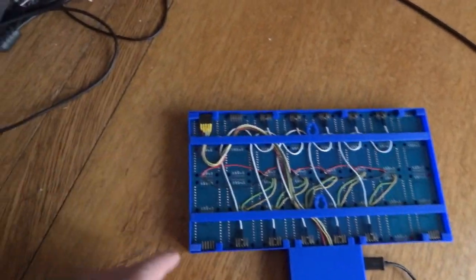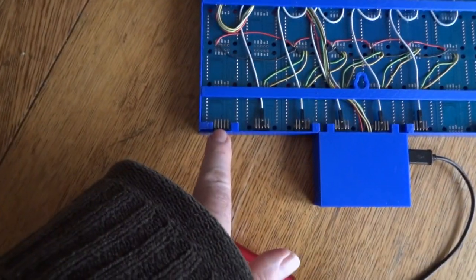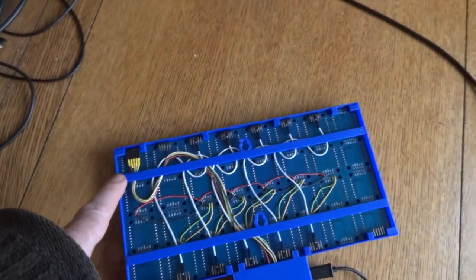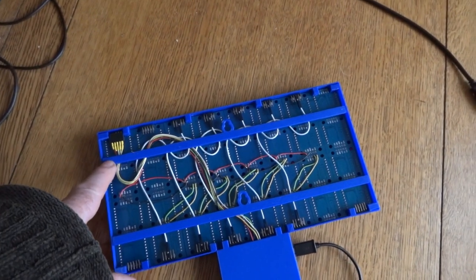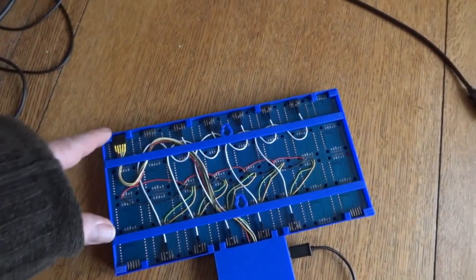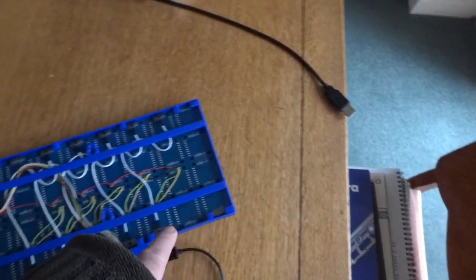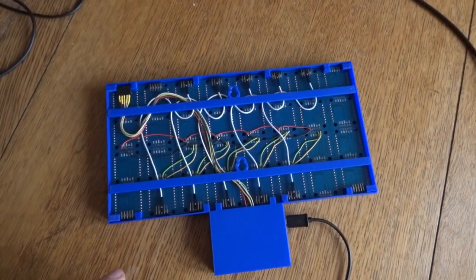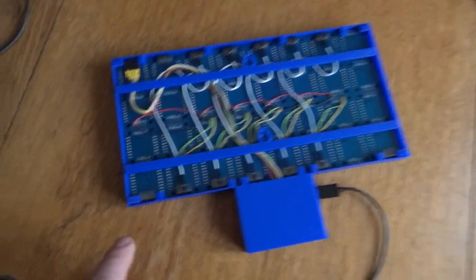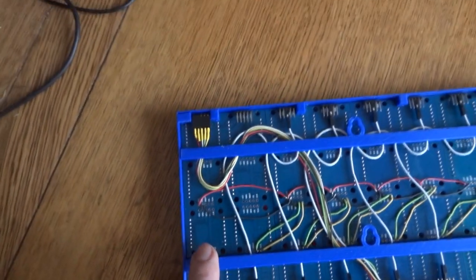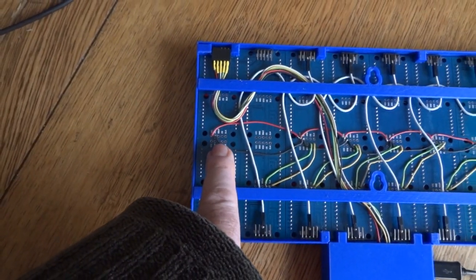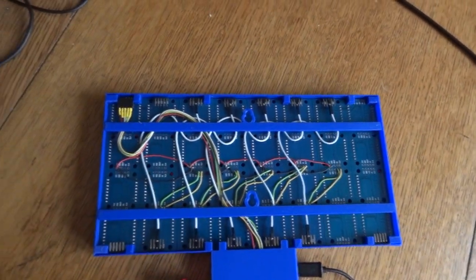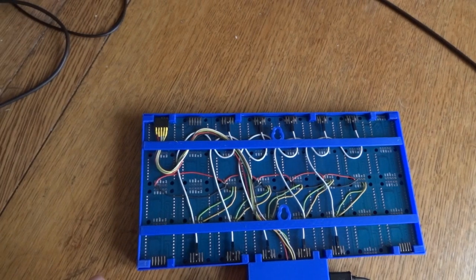You'll see, although you can daisy chain all the wires, including the power, I found that you can get a significant volt drop by the time the power's gone through all the modules to get to the last one. So on brighter settings you end up with one side of the display dimmer than the other. And so I've connected the power lines using these red and black wires here, so it's more like a bus bar than a daisy chain.